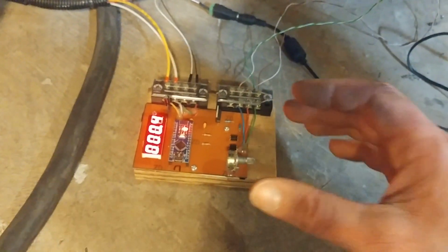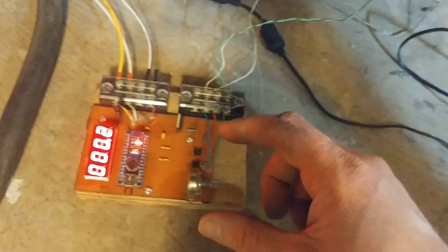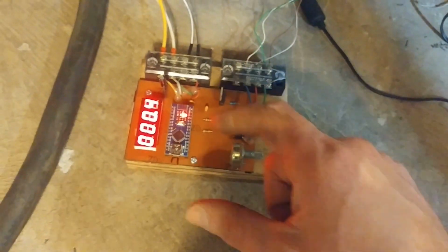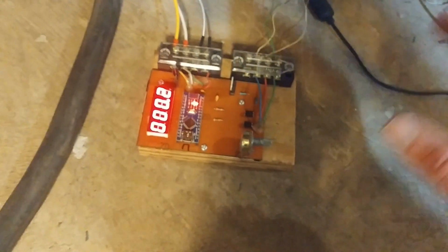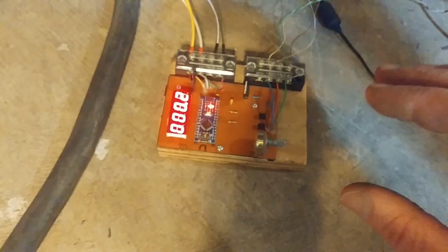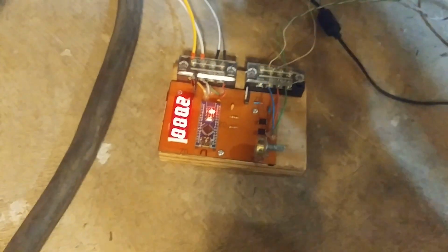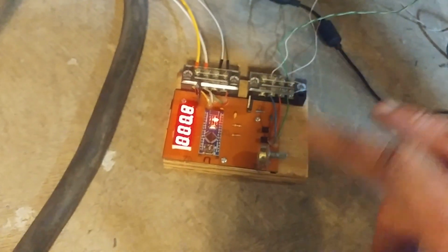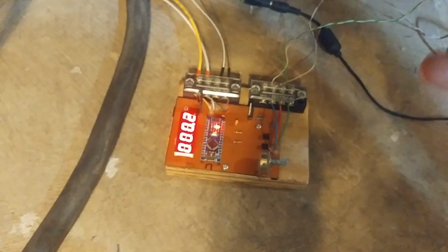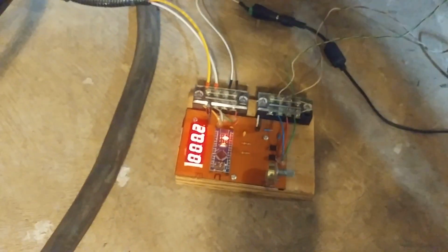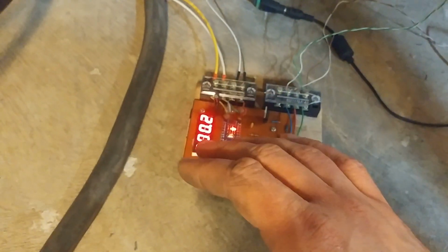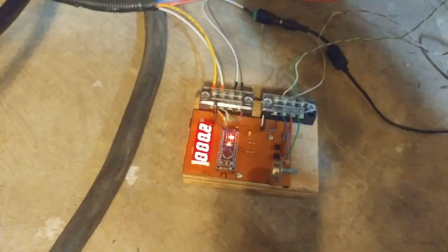Now that the board is in front of us too, I can point out these two little black chips, which are the opto-isolators that we use to send signals from the Arduino to LinuxCNC without ever physically connecting this board to the parallel port breakout board. That's because an opto-isolator isolates the two using light, opto-optics light, you get it, right? And the point of that is that it keeps any possible fault on this side from coming back to the computer and possibly frying it.